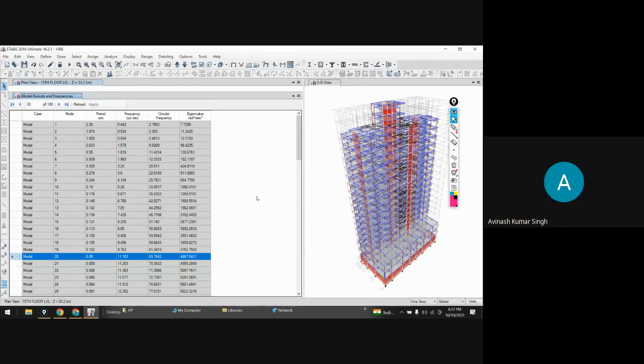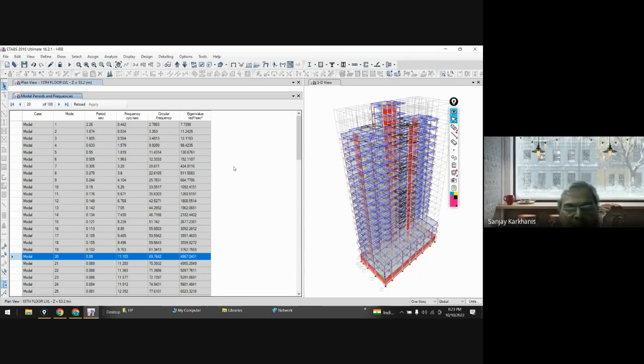Clear? सर एक चीज पूछना था इसमें, मॉडल मास हम लोग एक फ्लोर पर 2 लेते हैं, मोड लेते हैं 2 एक फ्लोर पर, तो इस पर वाटर टैंक को भी ऐड करेंगे या सिर्फ लास्ट रूफ रहेगा वहां तक सर? नहीं नहीं, we are analyzing up to terrace because whatever load is above terrace, it has been already calculated, already transferred on the columns.